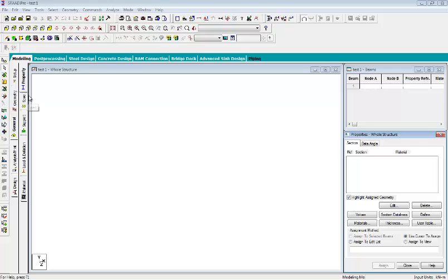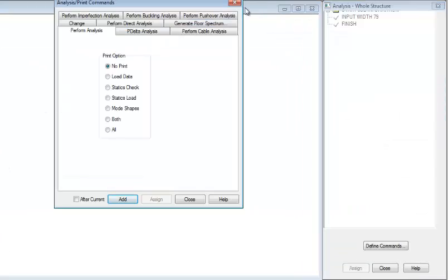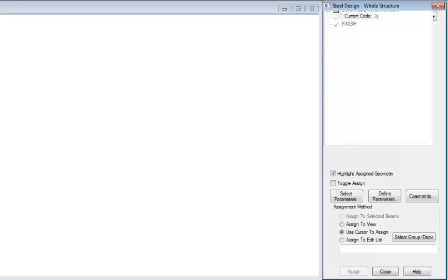These are various things like properties, specifications, supports, that is, properties of the material that we are going to use, the dimensions, and all. Then the analysis, where we check the bending moment, the shear force, everything. And then the design: on the basis of the bending moment, shear force, BMD, SFD and all, it will give us a particular design. Fine.